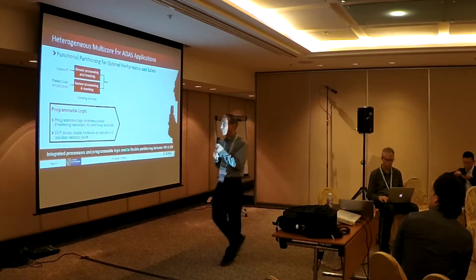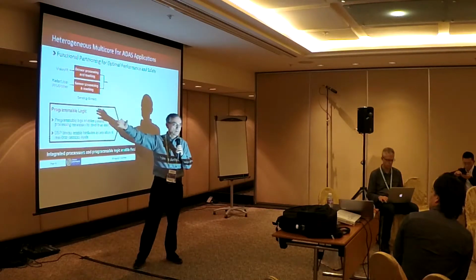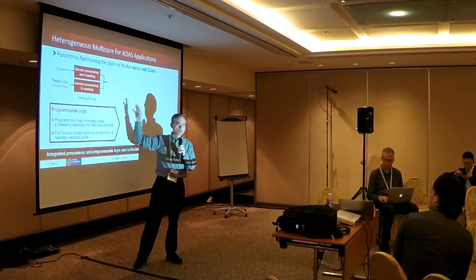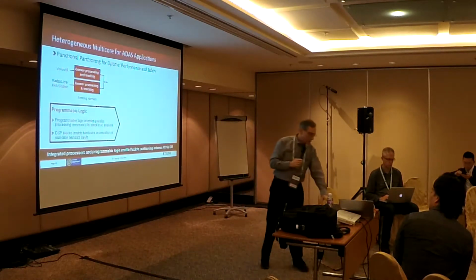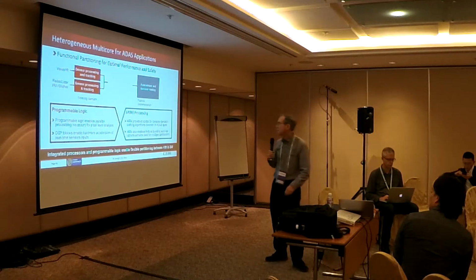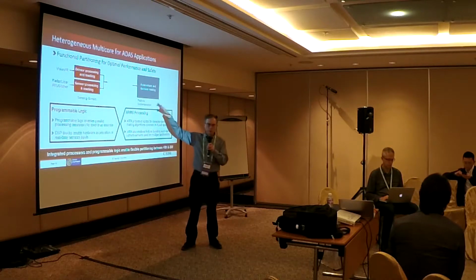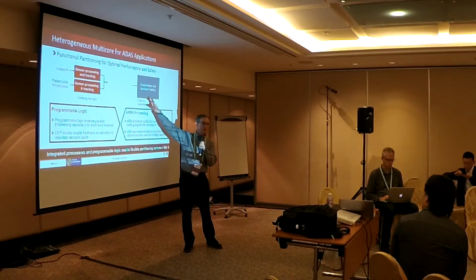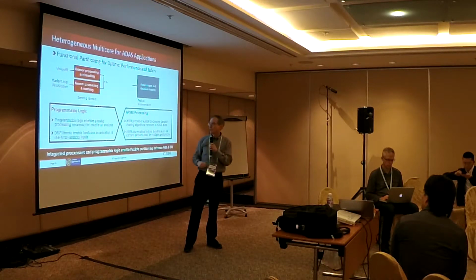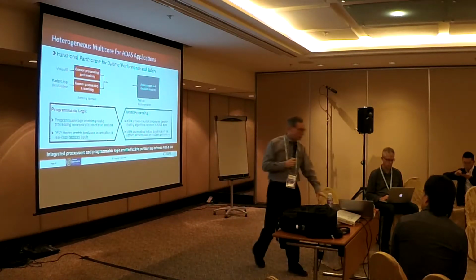And so this is where programmable logic comes in. You can create this dedicated pipeline of data flowing into the system, pushing out to DDR where it can then be post-processed. On the other side, you have general purpose types of functions. You may have a user interface, console information that needs to be displayed. You may need to be making some high-level decision making based on some of the inputs. This is where the ARM processors come in. And then you get the stuff in the middle.